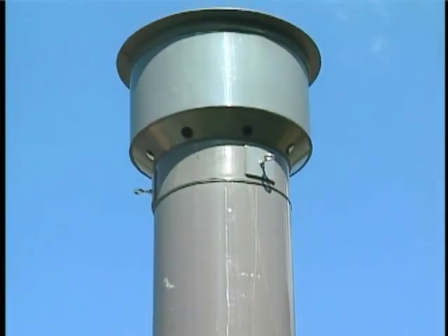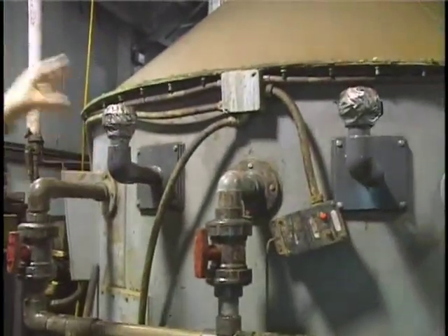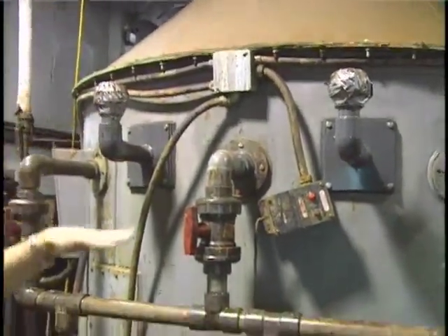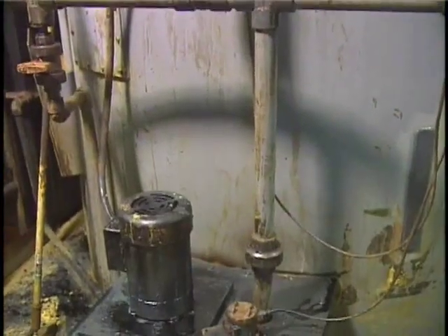If the flow rate is not being monitored, other indicators can be used. Indirect indications of decreased liquid flow rate include a decrease in the pump discharge pressure or an increase in the pressure in headers supplying spray nozzles. Increased pressure in a supply header is usually due to plugging of the nozzles, which reduces the liquid flow rate.